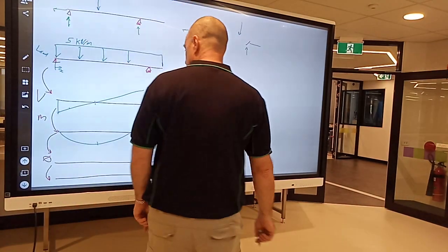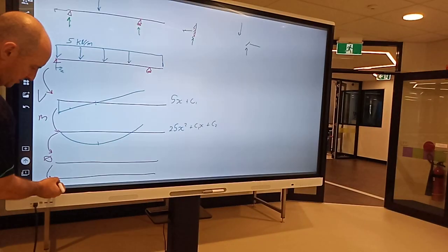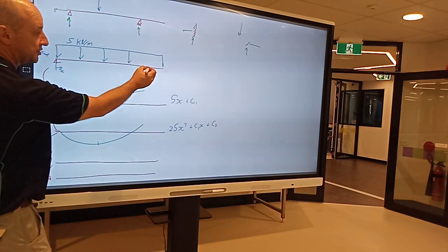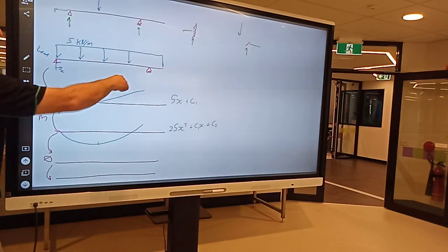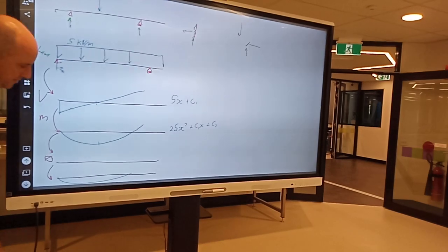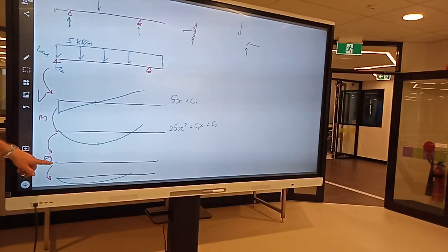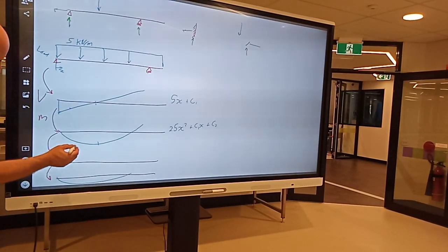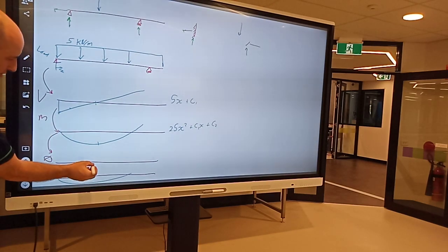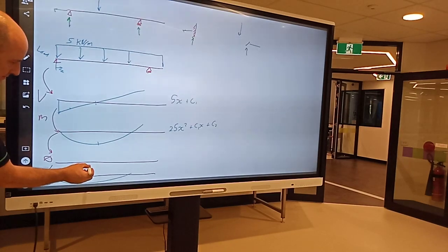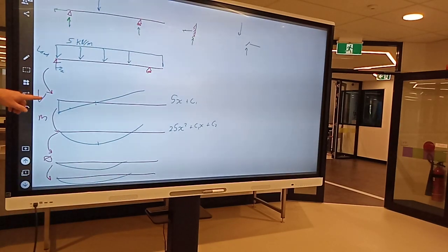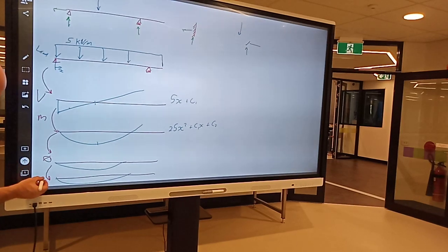Okay? So we'll skip down to the deflection, where again we're going to have 0 deflection there, and 0 deflection there, and that's going to give a basic shape like that. And the curvature is going to be minimum curvature, maximum curvature in the middle. Yeah, it's also that shape. All right, but that's the deflection there, the important one.